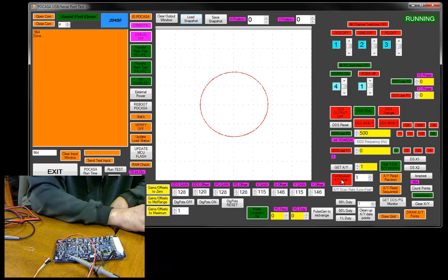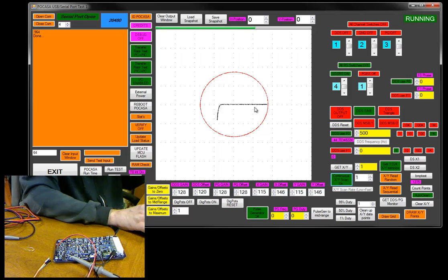Okay, that's what I had. And now I'm going over to my second board, which I know is, or that's what my good circuit should look like, that's on the screen right now. And I go over to my second board and I hit scan. Oh, what the hell's this? Red is what I had and black is what I got. So I had a capacitor and now I've got a diode. What the hell's going on here?